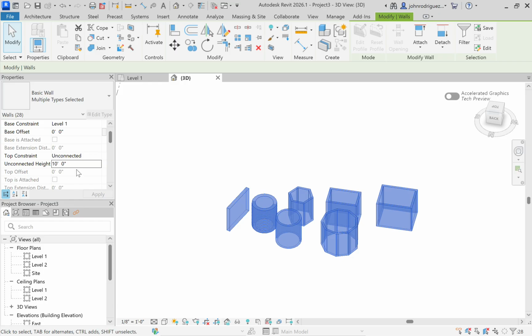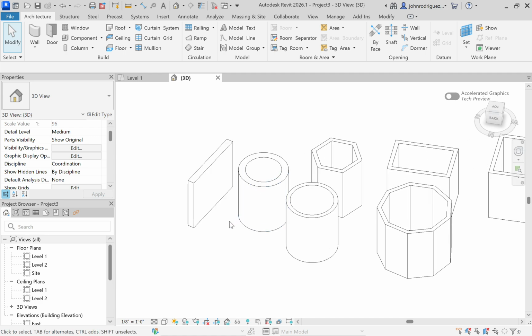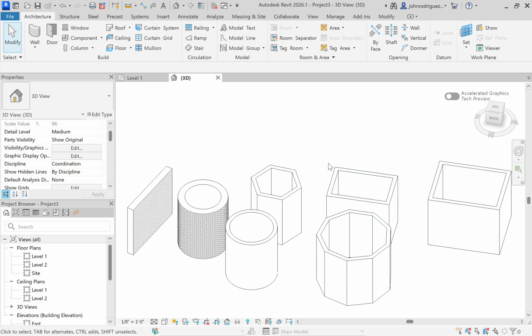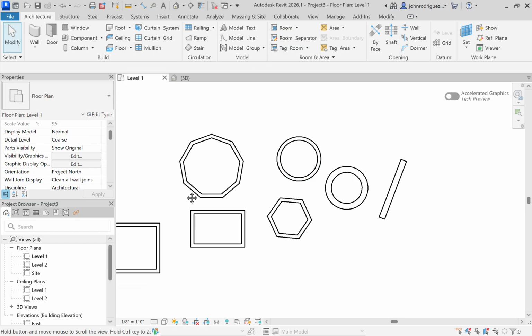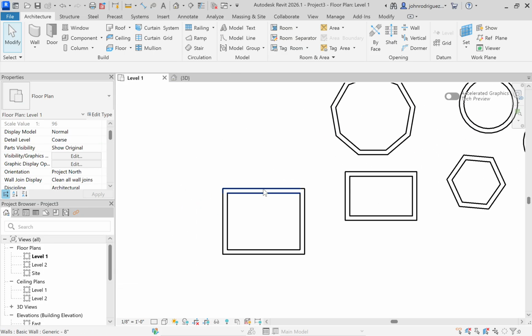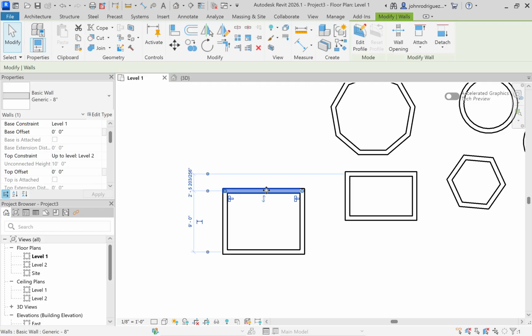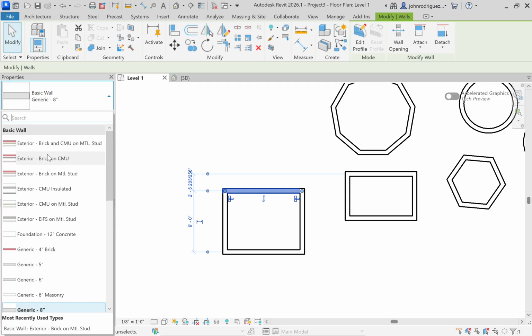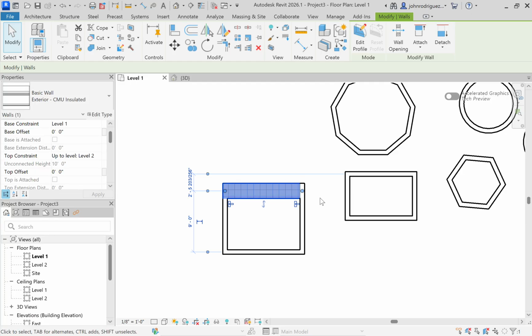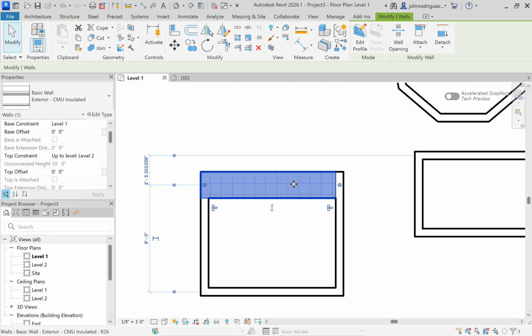But once we start talking about levels, right, we can connect this to level 2 or whatever, or floor 2 or whatever we set these heights to. When you do that, they will automatically connect and be that tall. Okay, that might make it a little easier in case you're changing heights of things in the structure. Okay, if you created a wall of a specific type, you don't have to erase it. You can select it, and you can change the type in the type selector on the left. Okay, notice it will become wider or thinner if it's different dimensions.